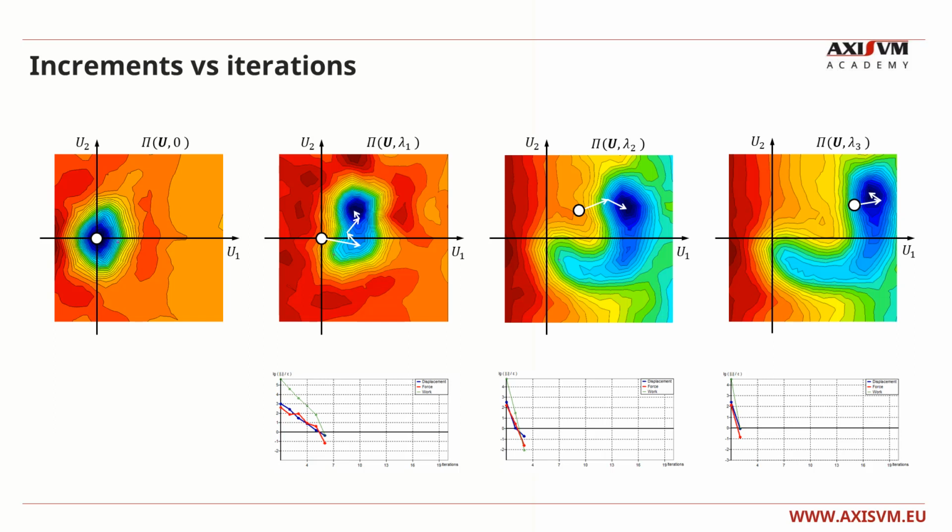In recent times, we got support models in which the user set only 2 or 4 increments. If the calculation converges well and lots of load cases will be calculated, it is valid to decrease the number of increments below 10. But for troubleshooting any convergence problem, the number of increments has to be set at least 10.